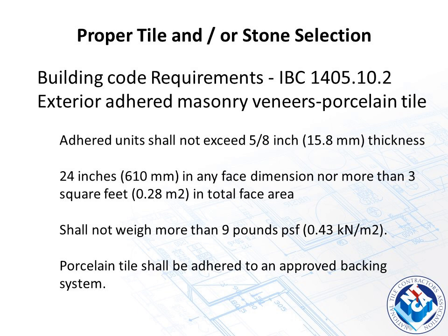But let's finish out talking about the code requirements. They should not weigh more than 10 pounds per square foot. I'm sorry, 9 pounds per square foot. And of course, the tile must be adhered to an approved backing system, one that's code approved.